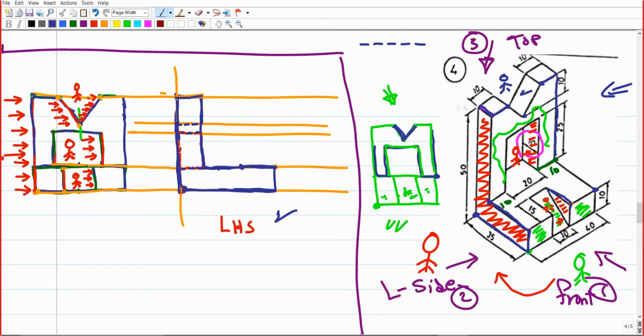Then you're going to drop down from the same point with 10. So I'm going to draw a dash line of 10 over this solid line, which will be seen solid. Then we're going to end up with another point. If we connect these 2 points, we're going to end up with the inclined surface. Make sense? So we represented all the features over the side view.